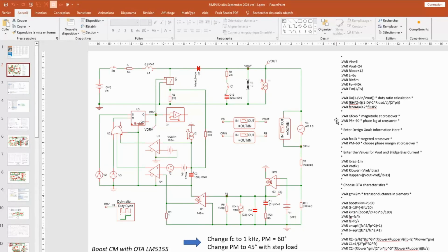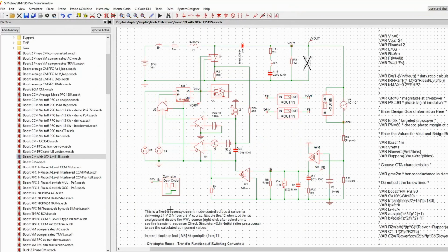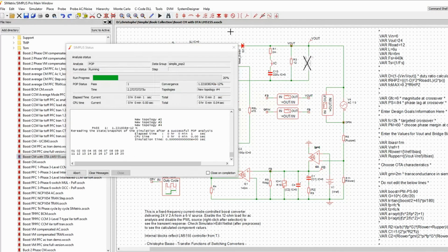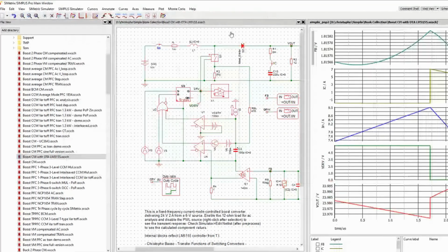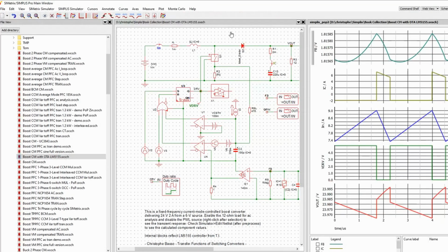So here we're going to immediately see a working example. You can see I have one Bode plot to extract the open loop gain of my power supply. I like also to look at the compensator transfer function. I mean, for the guy that I'm designing, what is its own AC response? And then here, the cornerstone of any analysis is the control to output transfer function of your power stage. So if I run the simulation here, the first thing that you need to check is the correct operating point, as Tom mentioned several times.